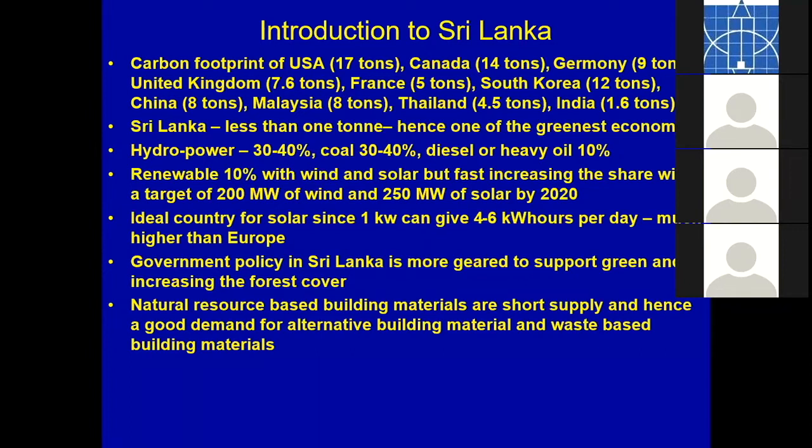Today we have better methods like boron treatment for timber. If we make the timber framework out of boron treated timber and then cover it with mud, you'll find that kind of building can easily last 100 years. We are planning a hotel project, and in hotel projects, we like things to be different. We are planning to use 3-story load-bearing wattle and daub construction for these hotels. We are doing some experiments now, thinking and improving and so on.